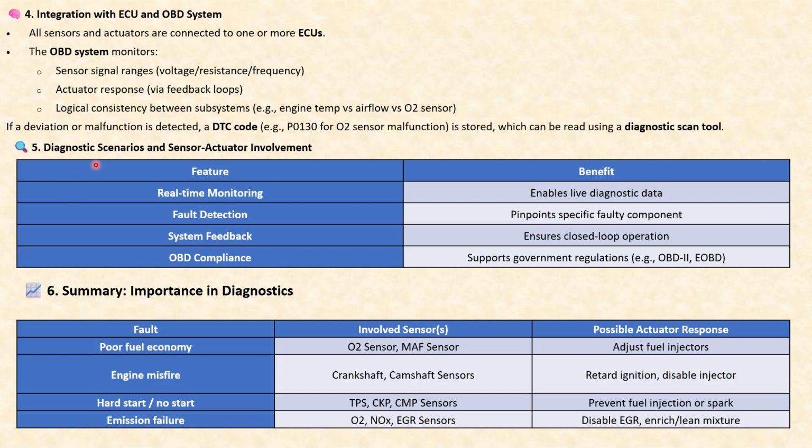Okay, now the diagnostic scenarios and sensor actuator involvement. The first is feature and benefit. Now talking about the feature, real-time monitoring enables live diagnostic data, fault detection pinpoints specific faulty components, system feedback ensures closed loop operation, and OBD compliance supports government regulations, including OBD-II and EOBD.